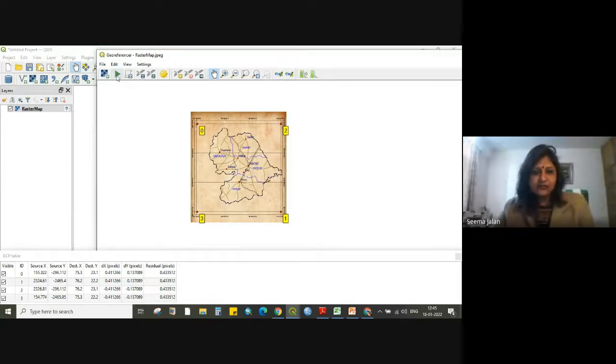I will go and say start georeferencing. Now, what have we done and what needs to be done further? First, I opened my raster. I told the GIS what will be the coordinate system of the values which I will be entering. Then I identified the GCPs and input the image as well as the map coordinates for those GCPs. Then I defined the equation.